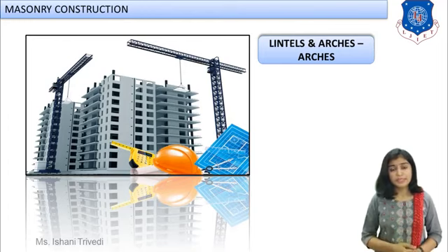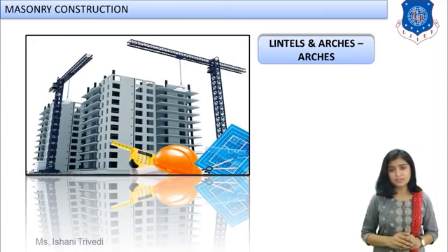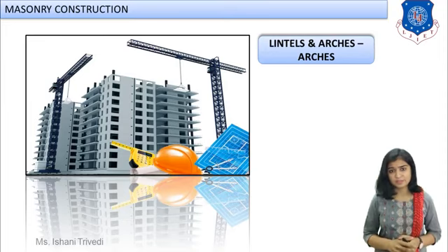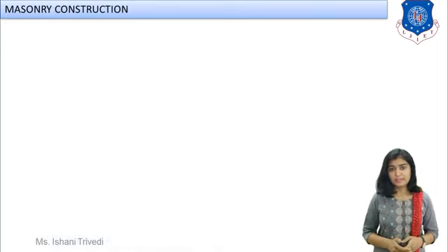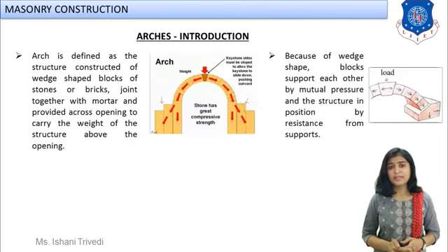Okay. So in the last session, students, we discussed which concept? That was lintels. Now let us recall quickly what a lintel is. It is the horizontal structural member provided across any opening in the structure to carry and transmit the loads safely. Now likewise, similarly, just like lintels, what we are going to provide is an arch construction.